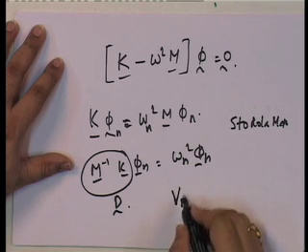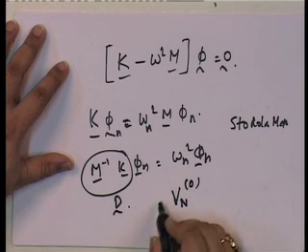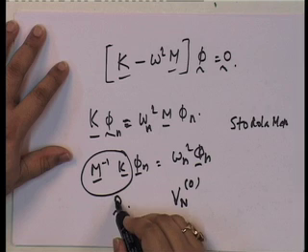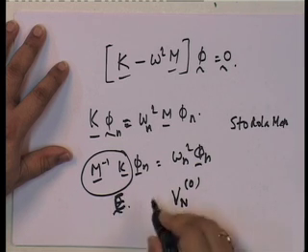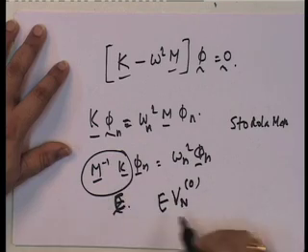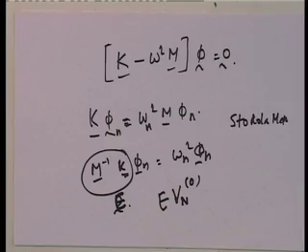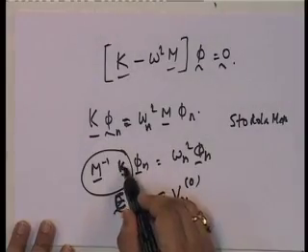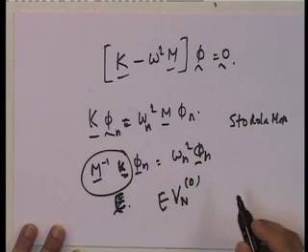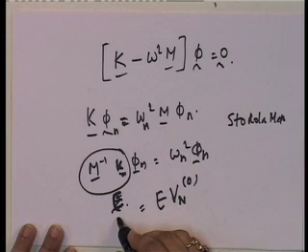a Vn 0 and then you multiply it by this. I will call this E because this is different from that. So, multiply it by E, which is m inverse k, okay? And typically m inverse, what do we do? Typically if we use the lumped mass, m inverse is just 1 upon m at every diagonal step. So m inverse is actually very simple to get, and if you multiply with k, that one becomes E.